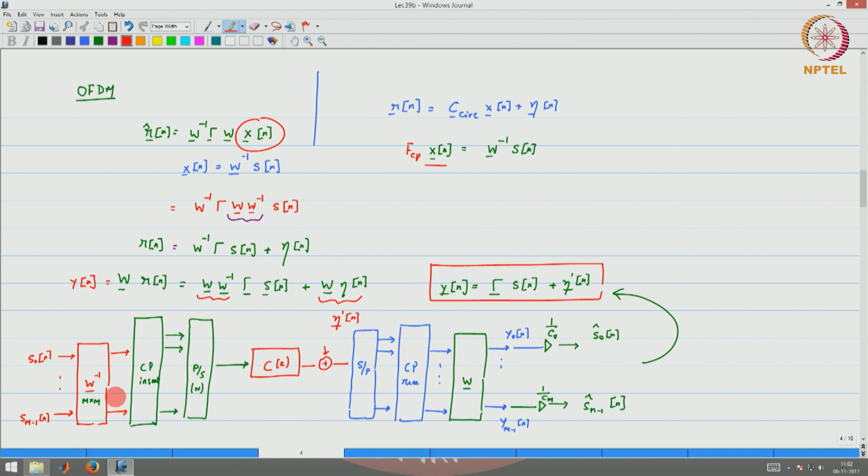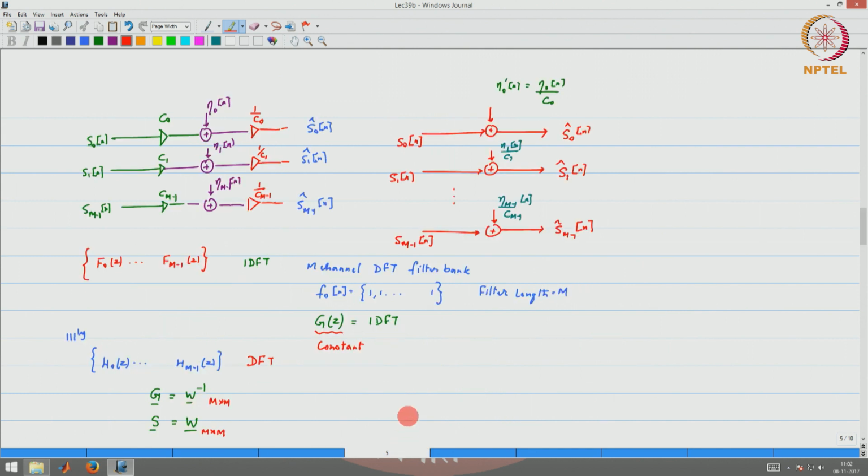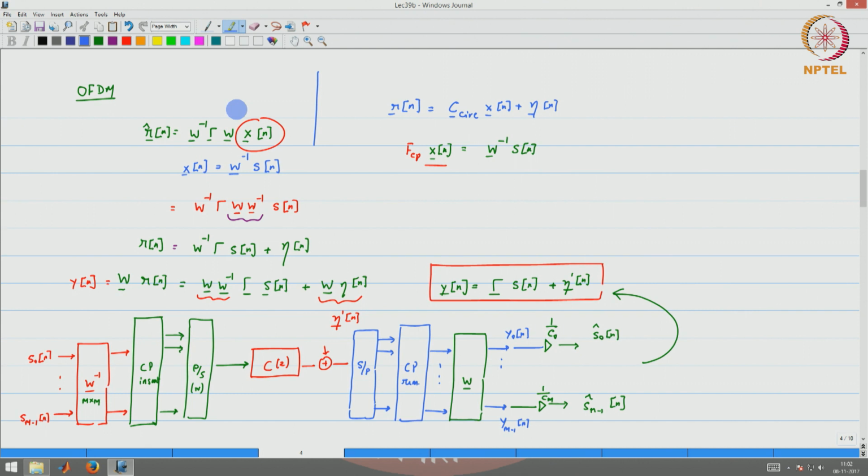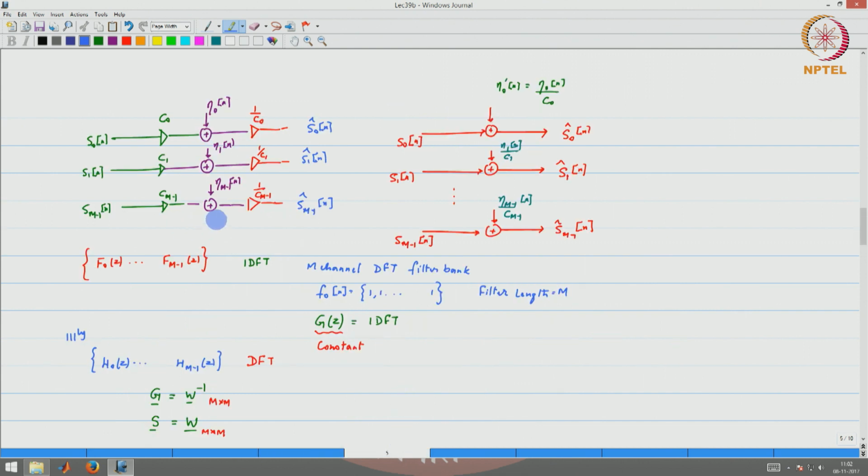So basically what we could do at the transmitter is to produce a signal for which you have taken the IDFT. So when you pass that through the channel, what we get is a very elegant, very simple structure. It looks like a set of parallel channels, though they were actually interleaved, transmitted through an ISI channel. What it looks like is a very clean parallel channel with different SNRs which are controlled by the coefficients themselves, and this is actually doubly advantageous because you can also do water filling based on these channel coefficients.